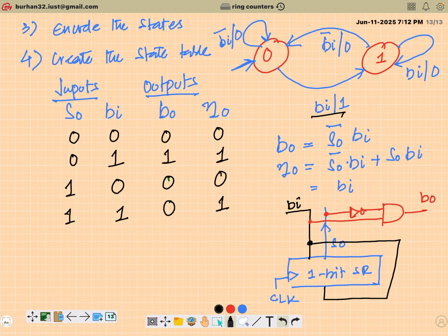So this is again a button press synchronizer, but designed using the concept of a Mealy machine. Remember, if you're capturing your behavior as a Moore machine, it means that the state outputs only depend upon the present states. You are in a particular state, output is defined. And in a Mealy machine, your output is conditional. Being in a particular state, it will depend upon what the condition at the external input is. So together, the state as well as the external input will determine what your external output is going to be.